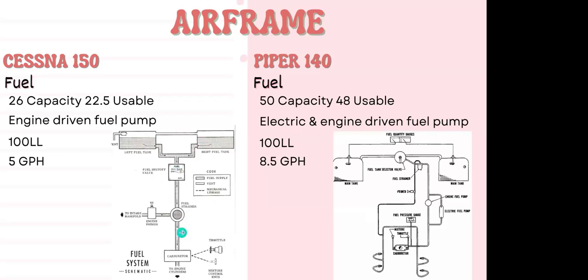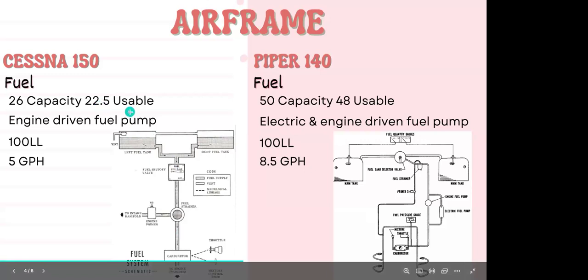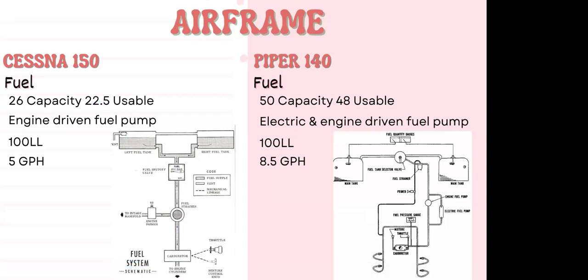Now, inside the cabin, we have an on and an off switch. And in some planes, and actually in the Cherokee, we can choose which tank we want to pull from. So we have left, right, and off. In Bluebell, we just got on and off. So you won't make it very far out of the chocks if it's off. So we've got it on, hopefully. And it will feed between two tanks equally, allegedly. It's supposed to feed from both tanks equally.